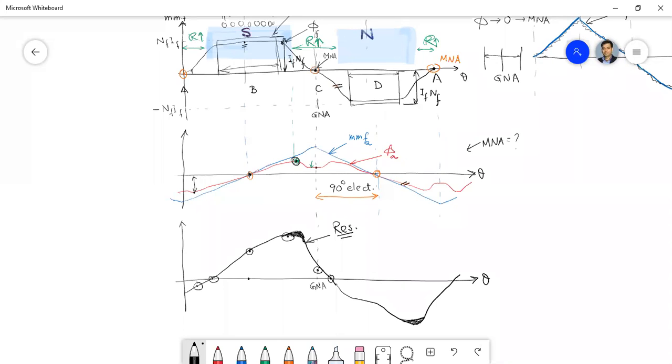Okay, so I am discussing this once more. Here you are adding these two fluxes, isn't it? When you are adding, at some point you are getting very high flux, like this point. Whether you will get that flux or not depends on your magnetic material, whether it will support, because magnetic material has its own BH curve nature.